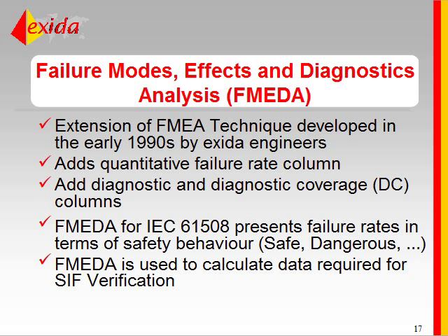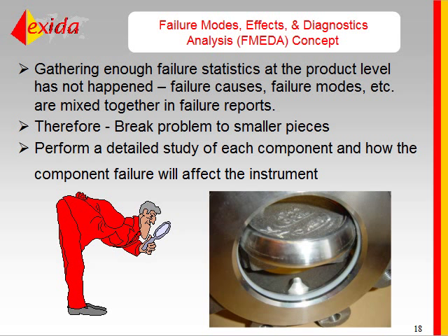And the result is an analysis technique that provides both functional failure rates and failure modes and the main categories required by IEC 61508, safe failures, dangerous failures, and so forth. The FMEDA technique has proven to be the best technique for generating failure rates of instruments that we use in our safety instrument and function designs.